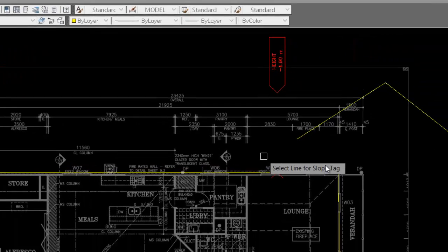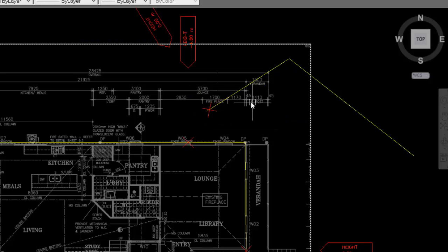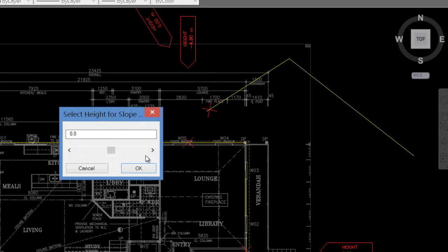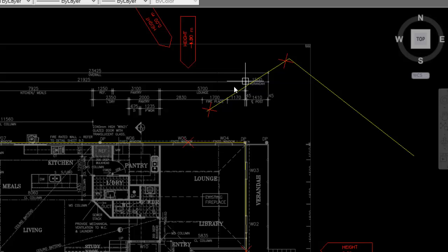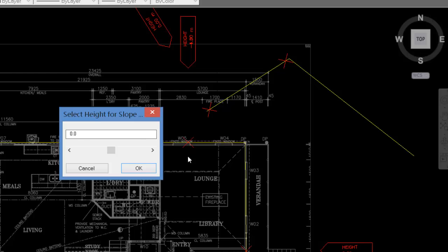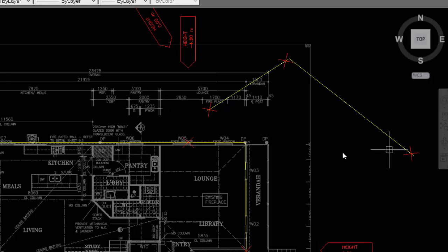slope tags. So again, slope tag of 0. I might decide to actually slope all the way up above the ground. So I might actually go to 2 meters. So now it's going to be 2, and we're going to go a little bit above the ground, and then we're going to slope on this wall here, and we're going to make it quite steep. We're going to make it go maybe -7, and just click there. Again, remember, I can type the distance or I can manually click.